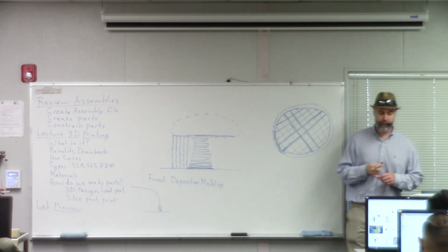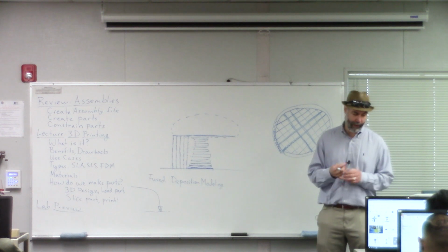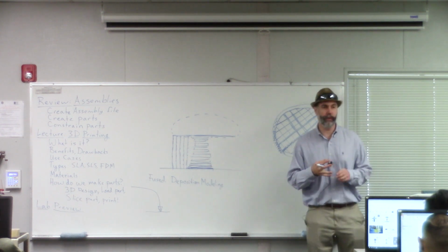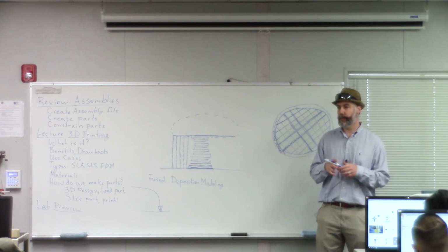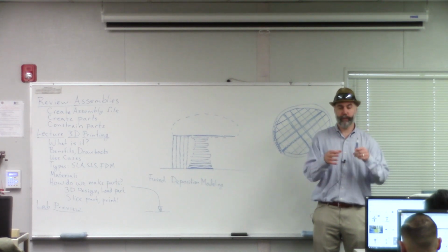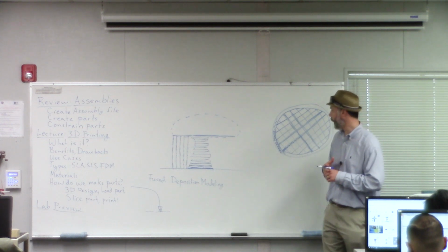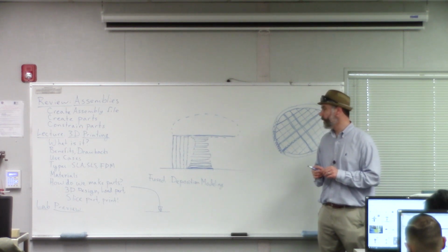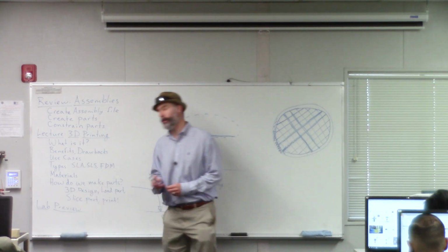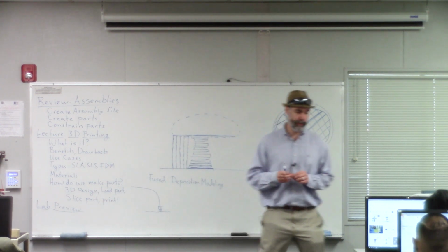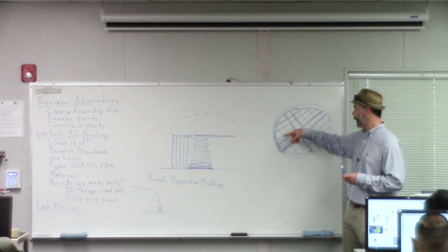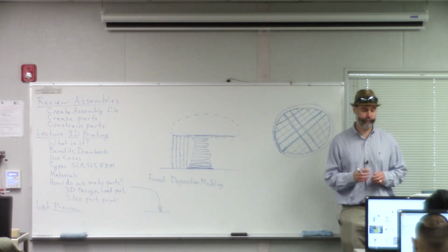Okay, and that's called the tool path, and that is usually created in a language called G-code. So this G-code is a machine language that tells the machine how to move and where to go and how fast to go and things like that. So the slicer will create the G-code for that part, which is really its own program that tells that machine exactly where to move to create that part. Okay.